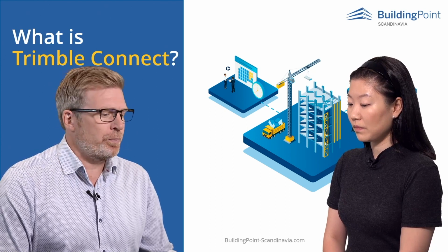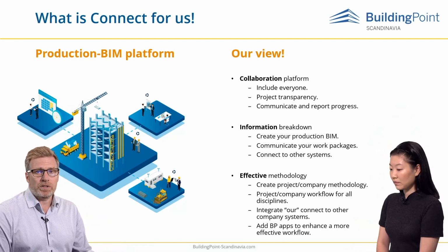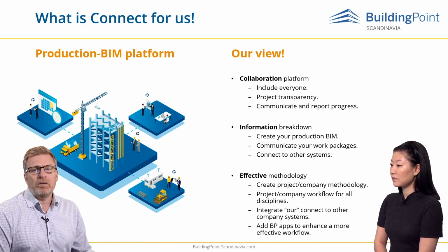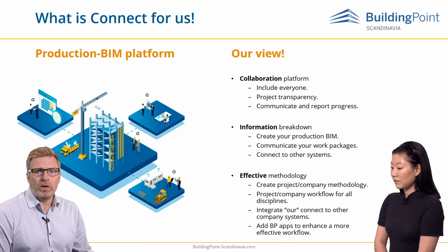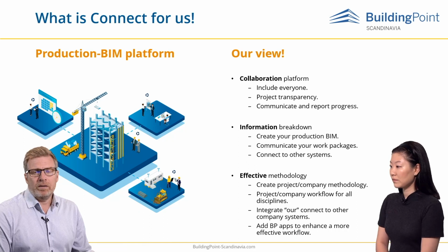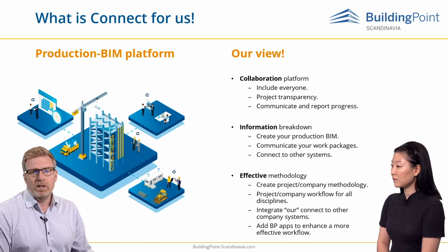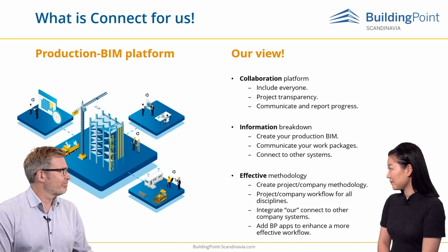So to begin with, just want to briefly touch on what Trimble Connect is for us in BuildingPoint Scandinavia and how we use it. We work mainly with Trimble Connect as a production BIM platform for general contractors or owners or what happened in the fields. So we use it as a collaboration platform, a CDE platform, and that involves everyone in the project. So we talk about information sharing and information structuring for production, and how we break down information from the BIM model to digital work packages. And we also help out developing methods, how to use it, and sometimes where the software is not enough, we add on different types of extensions and other things that we do, based on needs.